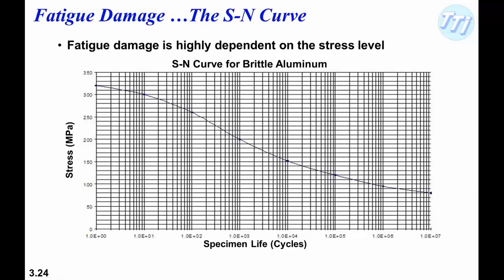So obviously, if we have a specimen that is going to have to operate for a long time, like an airplane, we want to set our test up so that the loads on the specimen are similar to what we expect in flight, and then test it for a long time and see whether it survives.